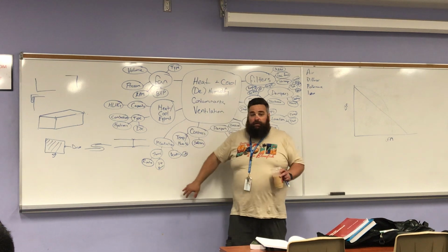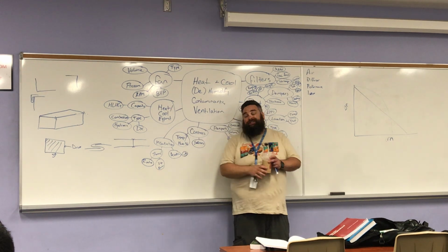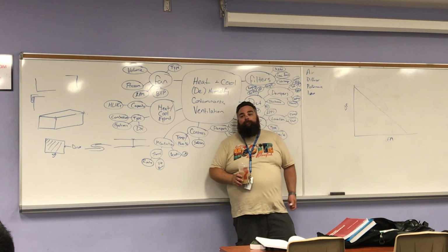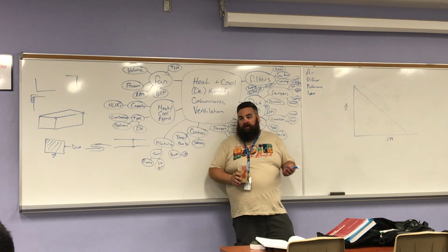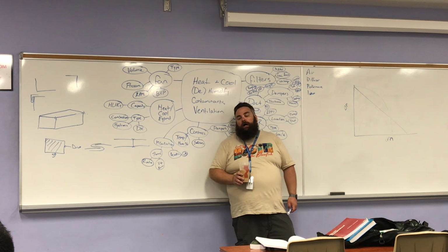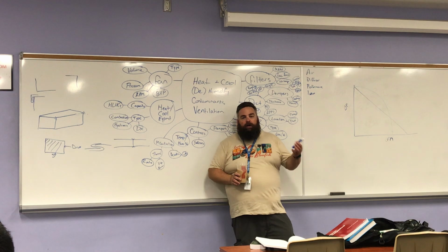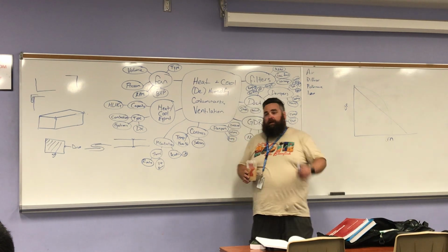There's downsides to acoustic insulation. One, like we said, there's an additional pressure drop. Two, it holds onto dirt and stuff really well, so that'll increase the pressure drop over time and cause dust bunnies and stuff in your duct.